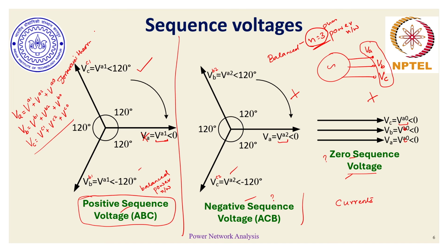at the outset it might appear that on the right hand side of these three equations there are 9 variables which need to be identified, 3 for every such phase. But as per Fortescue's theorem, if we identify only 3 variables, then the remaining 6 variables become known.